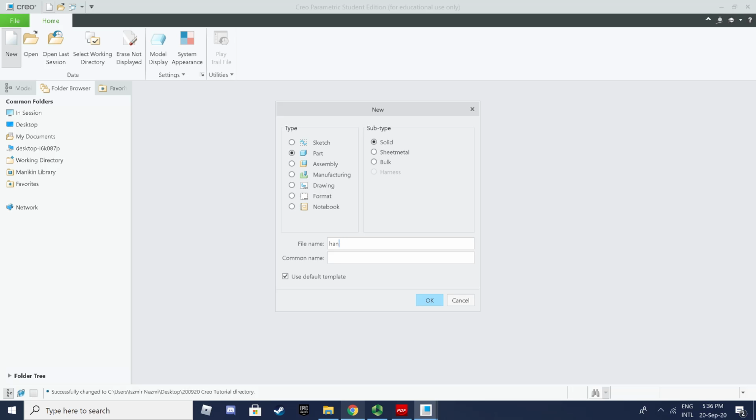But later, when you learn how to make an assembly drawing and also an exploded drawing, it's easier if from the beginning of your works you start indexing, or giving numbers, to your parts. Especially when you do group projects, you will do, let's say, a minimum of 15 components, so you need to arrange them according to the part numbers.